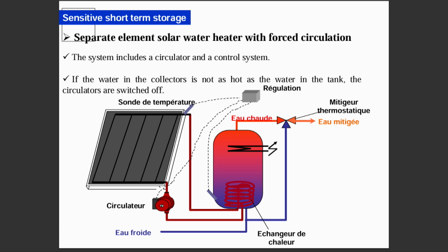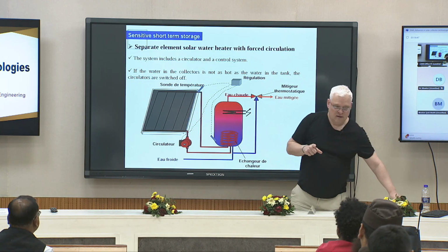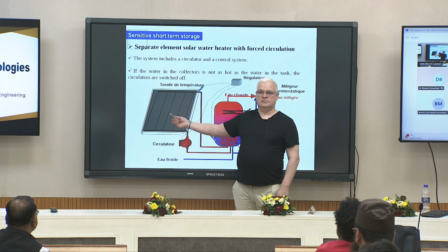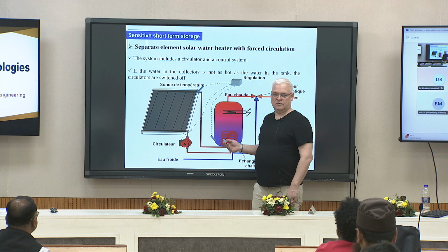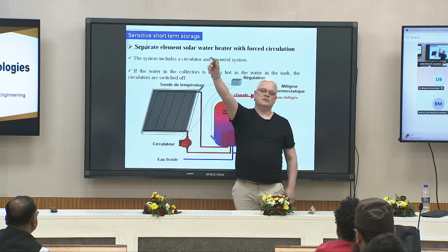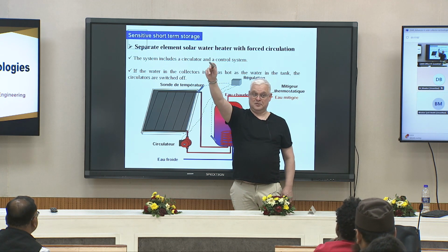And there were many installations where this kind of sensor was out of service. So that means that it was running even during the night. During the night, the solar thermal collector will be hot because it will take hot water from your tank, and so will emit a lot of radiation to the sky, the celestial vault.